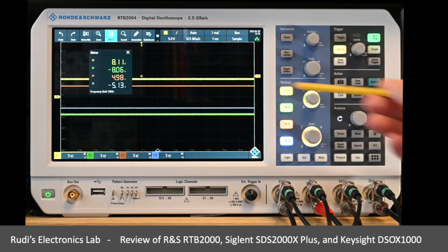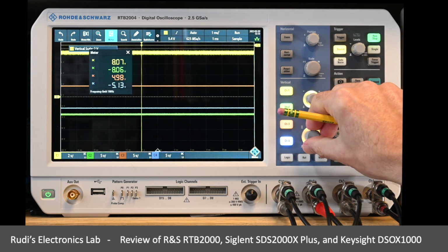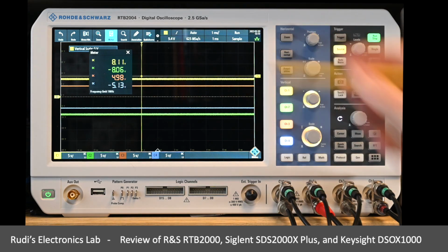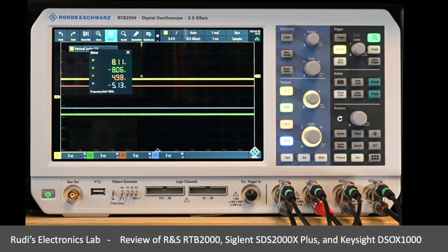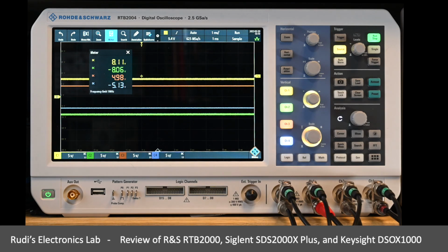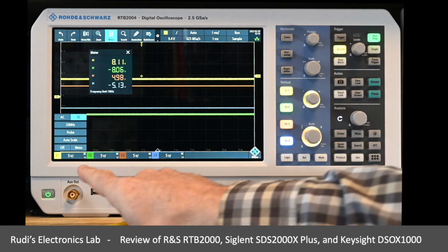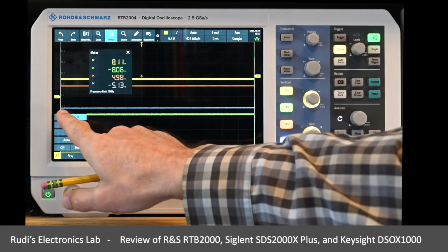That also means, and we just saw that when I was playing with the buttons, that the scaling takes place via the channels. So we have to make sure that our signals are, of course, scaled within the range of the ADC. This also brings in another issue that I would like to discuss with you, because as you will have noticed, I'm looking here at DC measurements. However, now if we go to a particular channel, I'm going to channel 1, and I'm going to move that channel to AC,